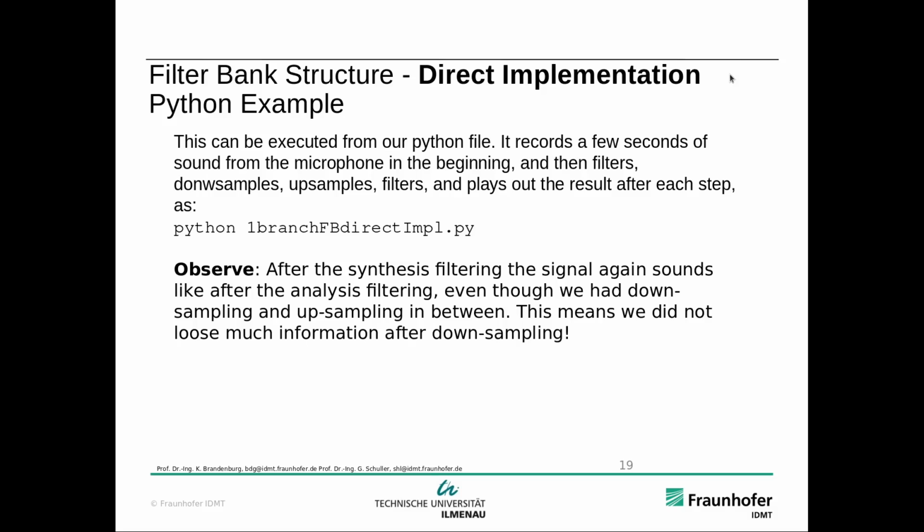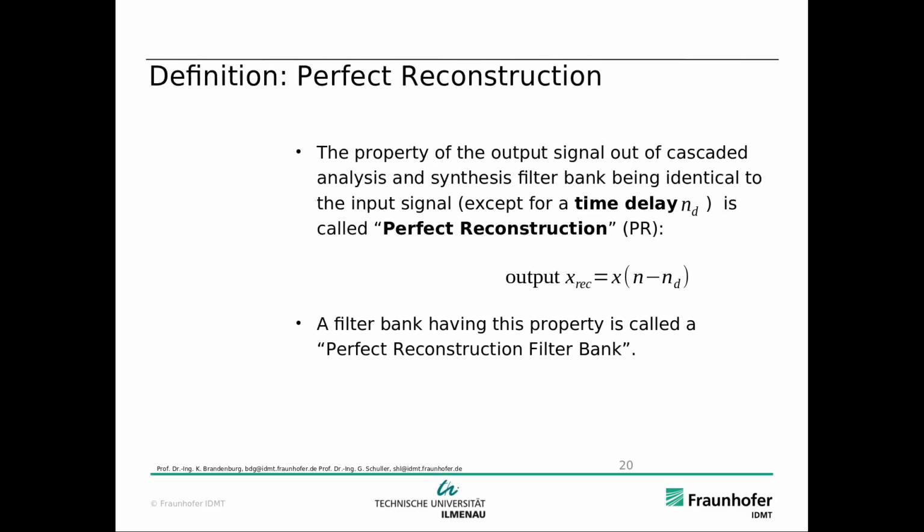So let me go back to the slides here. So after the synthesis filtering, the signal sounds again like after the analysis filtering, even though we had downsampling and upsampling in between. This means we did not lose much information after downsampling. And this also shows you the principle of the so-called bandpass Nyquist theorem, which means we can also sample a bandpass filtered signal and reconstruct it accordingly.